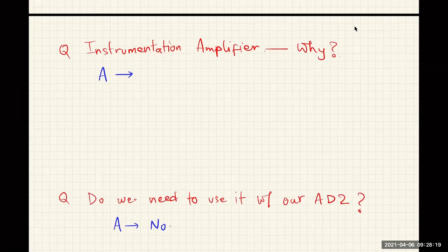So in order to measure differential voltages like that with single-ended probes, one method is to use two channels to measure the two voltages across the resistor, both referenced to ground, and then take the difference of those two voltages on the oscilloscope using math mode. Okay, or you can export the data and take the difference. The other method, so that's one method, but some oscilloscopes may not even have a math mode.